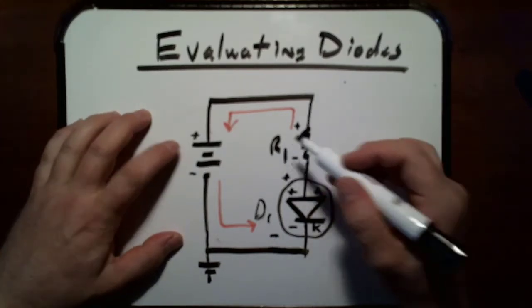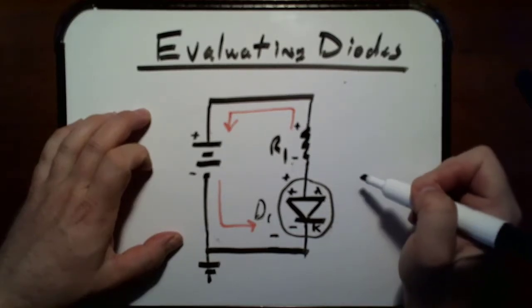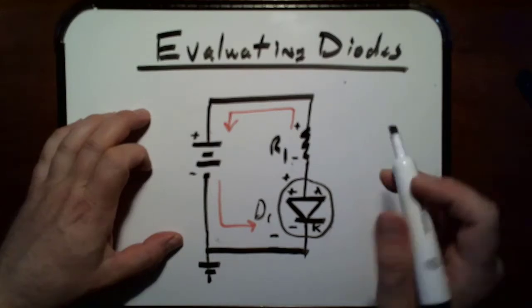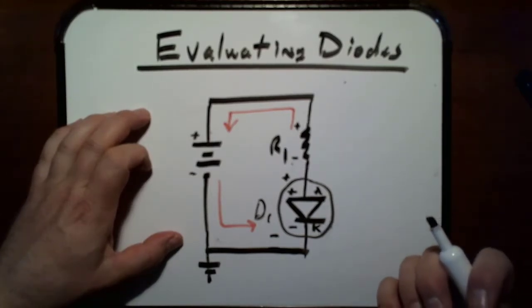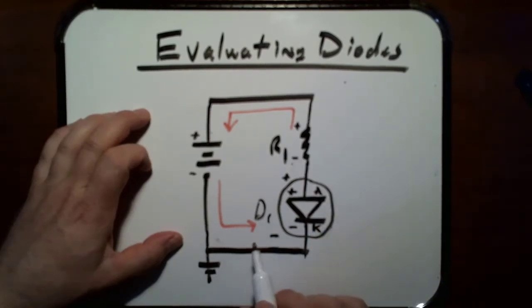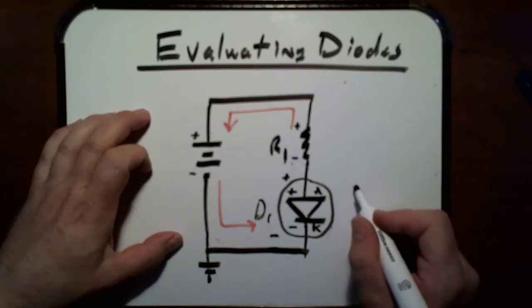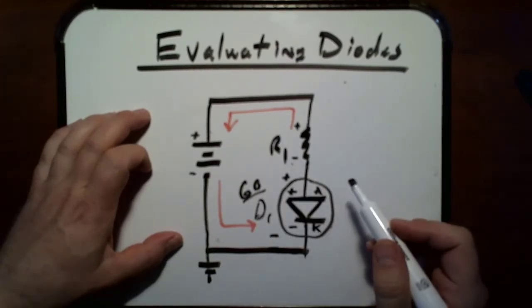It picks that up from the circuit that it's in. If I was to pull it out of this circuit and just grab a bag of resistors, they would not have polarity. Okay? Some components come with baked in polarity and orientation, some don't. So this diode so far is a go because it's got matching polarities.